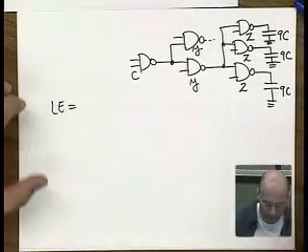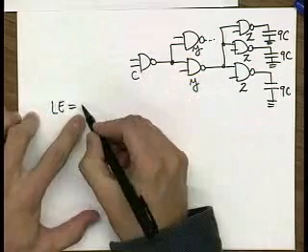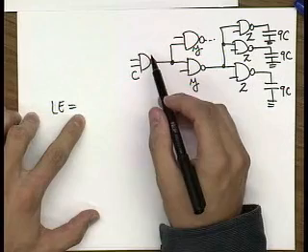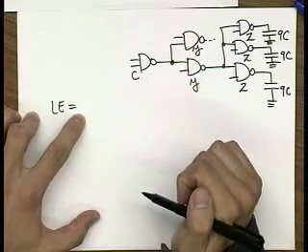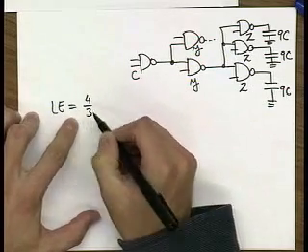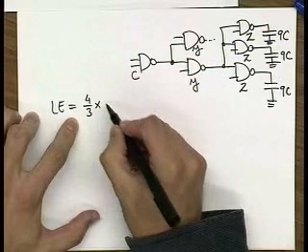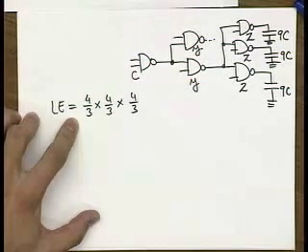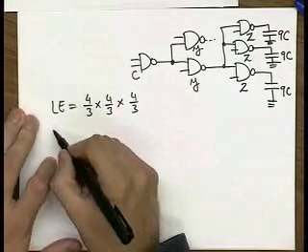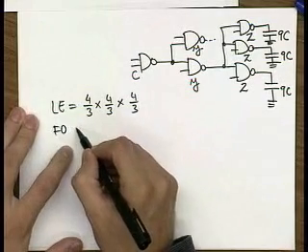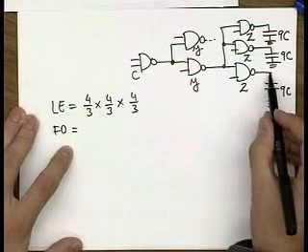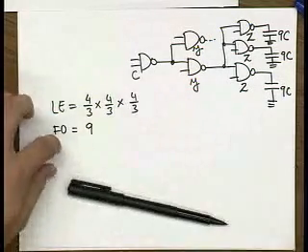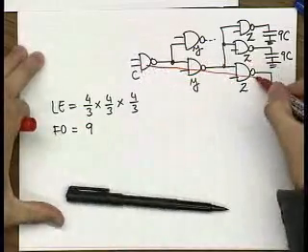Thanks. So now the logical effort is basically logical effort of all these stages. So what's the logical effort in this case for a path? For an AND, you have 4/3. First stage, second stage, third stage. So now what's the fan out? It's equal to the total output capacitance to the input capacitance. So that is 9. And let's say we are analyzing this path over here.